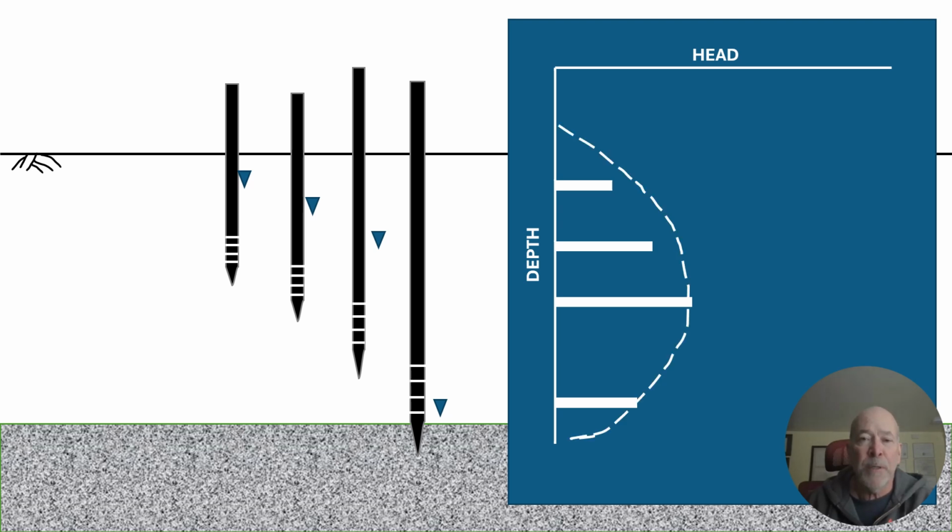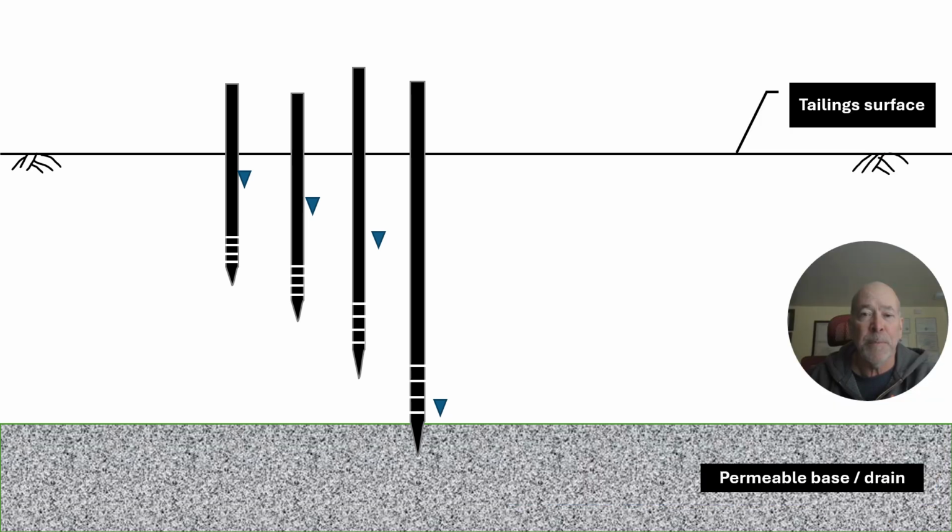So we had a pore pressure distribution like this. It's nothing like hydrostatic. And so this is the importance of understanding the pore pressure regime. And it's seldom hydrostatic, and using hydrostatic in a slope stability analysis is not realistic. But if you have a lot of data points like this, it sure can be helpful in solving slope stability.